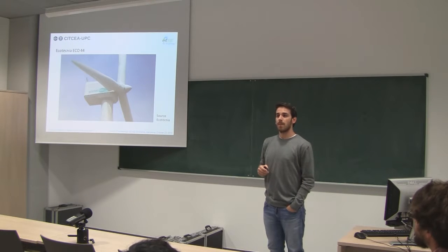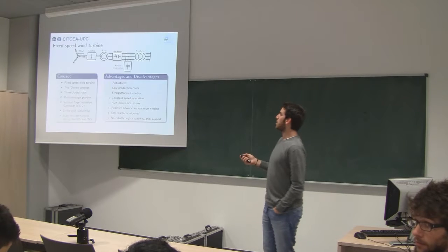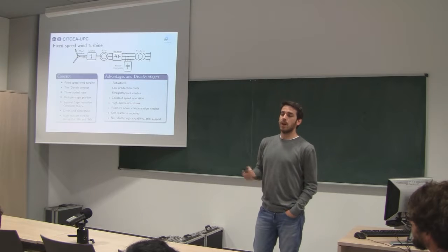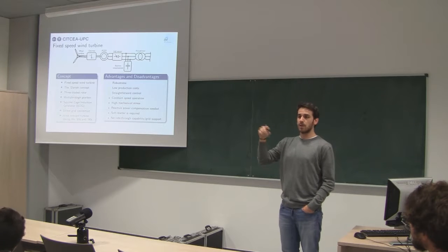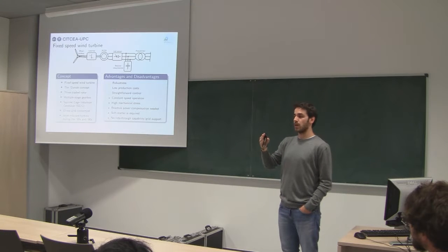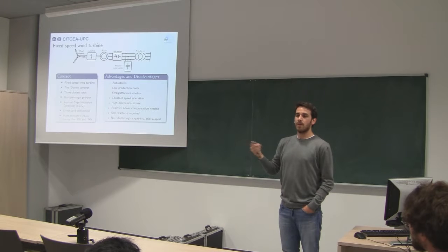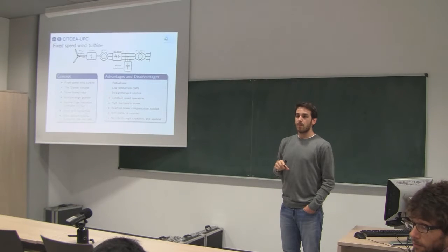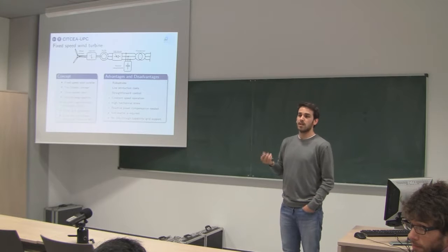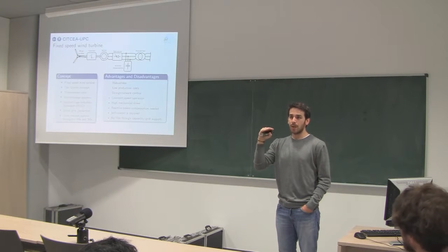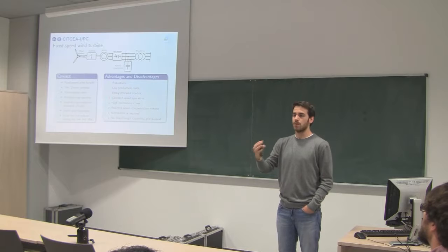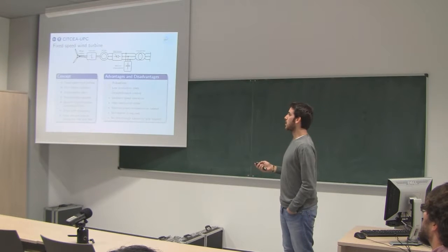What do you mean by soft starts? In the previous slide, this one? It says soft start is required. Yeah, because this is just for grid connection issues. If you connect the generator directly to the grid, maybe you could have something like 7 times the rated current flowing through the circuits. So you mean like a normal motor, right? Yeah, it is like connecting a classical motor directly to the grid. So you need something there to limit the current flowing through the circuit in the first seconds or milliseconds. Okay, that's the main idea.